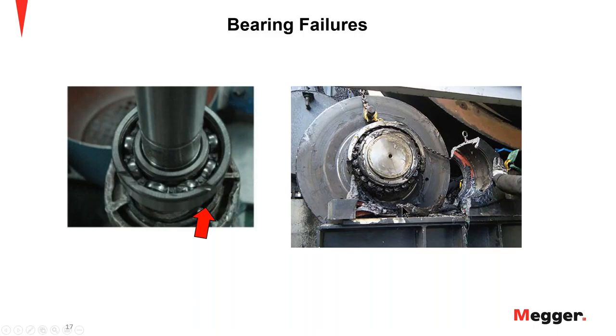And then for the second picture, man, this is a nasty hit right here. The case has come off. The bearings are just totally destroyed. It could have been due to overheating, or it could have been due to vibration. And all I have to say is that's not going to buff out. That guy is a full replacement, of course.